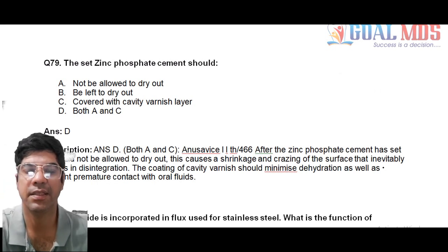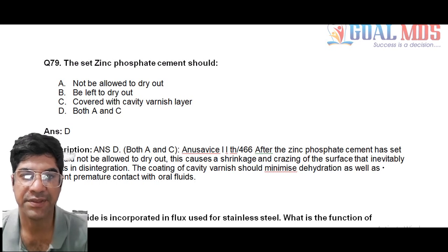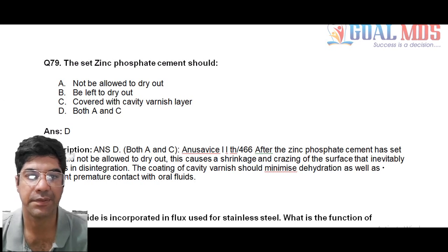After the zinc phosphate cement has set, it should not be allowed to dry out. That causes shrinkage and crazing of the surface, which leads to disintegration.